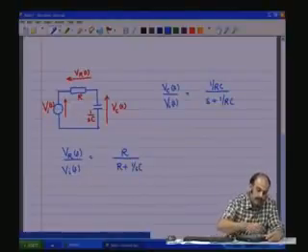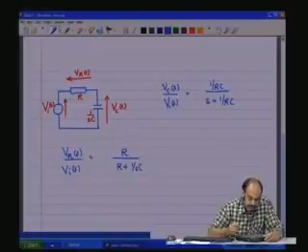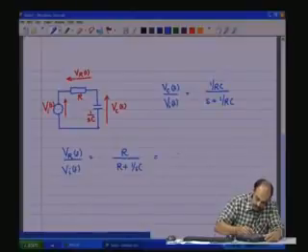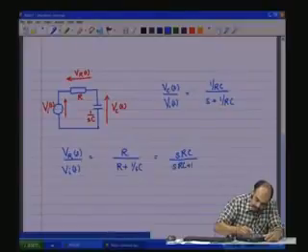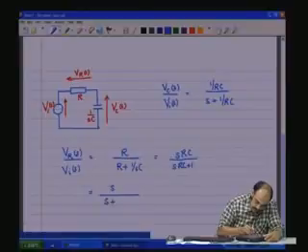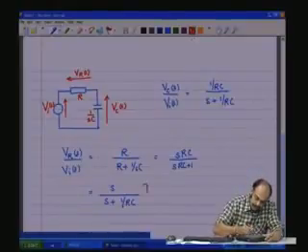So, this would be the ratio in which they divide, the resistance divided by the resistance plus the capacitive reactance. So, this on simplification would give sRC divided by sRC plus 1. Slight further simplification will give you S divided by S plus 1 by RC. You see, this is a slightly interesting result.